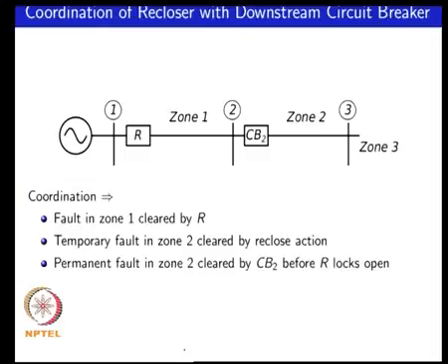So, your recloser might be sitting at the substation and your circuit breaker might be somewhere further downstream, and a recloser needn't just be the timing of trying to stay closed for some time, then opening, staying, reclosing again, etc. The logic underlying the recloser might also have a circuit breaker characteristic. Okay. So, in addition to the recloser characteristic, there might be an underlying circuit breaker characteristic.